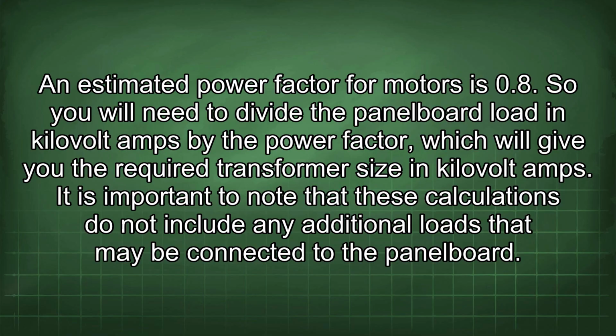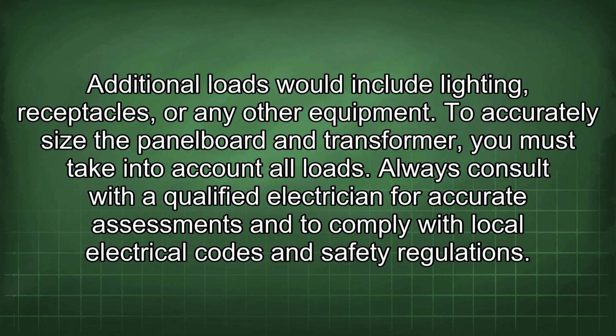It is important to note that these calculations do not include any additional loads that may be connected to the panel board. Additional loads would include lighting, receptacles, or any other equipment. To accurately size the panel board and transformer, you must take into account all loads. Always consult with a qualified electrician for accurate assessments and to comply with local electrical codes and safety regulations.